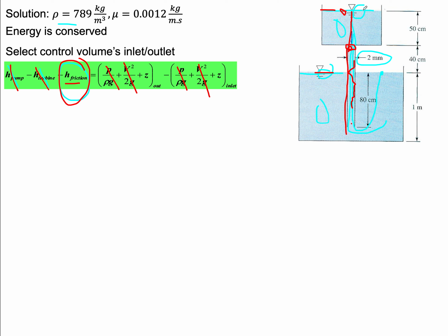So all the energy, the energy difference between those two levels, so the fluid particle will continue until it hits the surface, and all the energy contained in the particle at this level was lost through the pipe friction in the pipe.